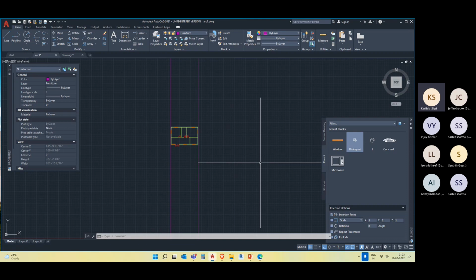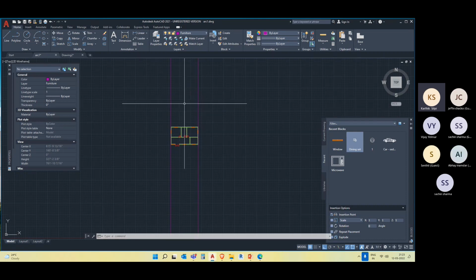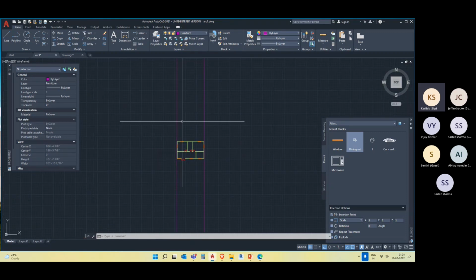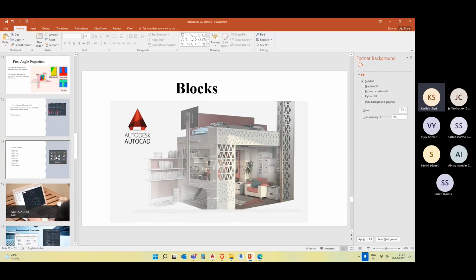So we in India, as we discussed in the first or second class, will always use first quadrant. So the basic rule of first quadrant is when you are having a front view, the bottom view will be in the bottom. So we've got a bottom view. So obviously the front elevation should be in the top. All right. So that is why we have, just go to that slide and show once again.